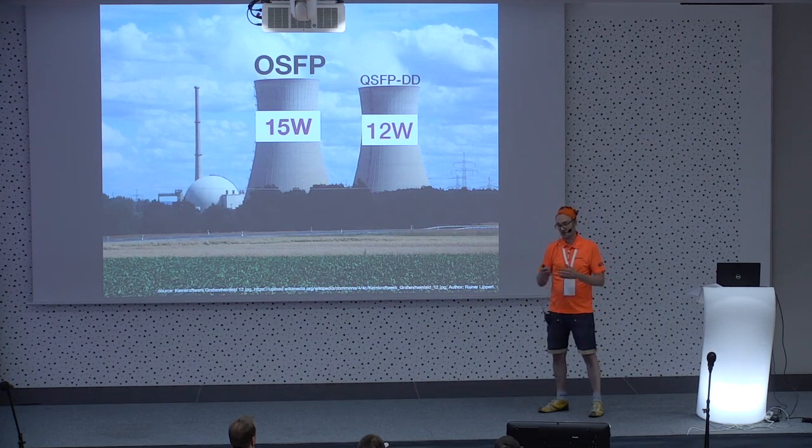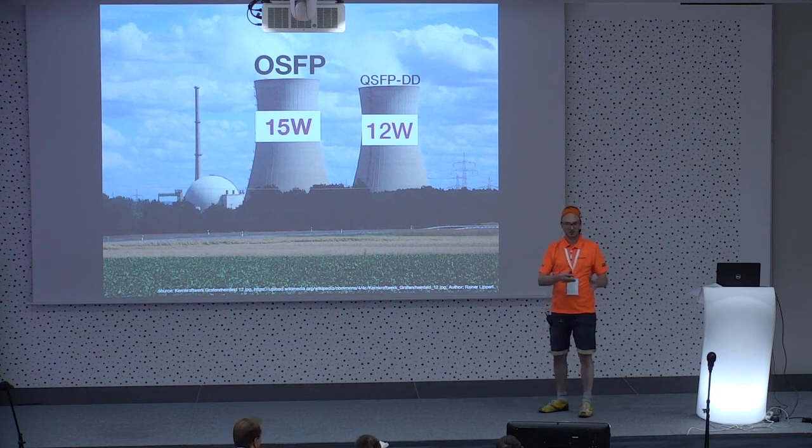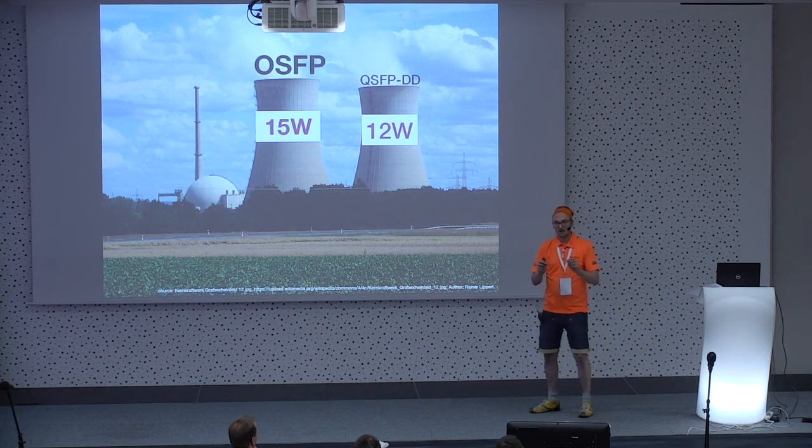In 100 gig, we are somehow lagging in long distance, like beyond 10 kilometers transceivers, talking about DWDM or even coherent technology. Yes, there are solutions when you're thinking about CFP, but I don't want to mention that form factor any longer. For 400 gig, these working groups have in mind that we also want to enable coherent DWDM technology within QSFP-DD or OSFP, and that's one of the reasons for being able to have that much heat dissipation.